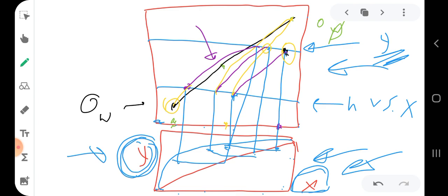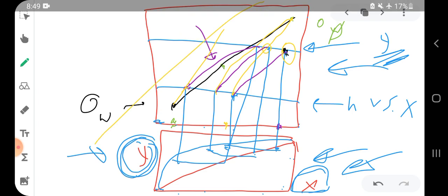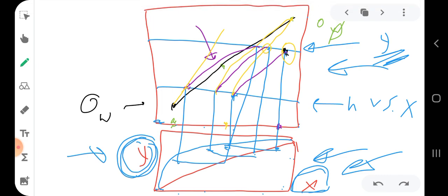Okay? And when I connect it to OW, I extend the line until I cross the vapor line. Okay, so again, I cannot connect it to OD. No, I cross the feed, so I connect it to OW and extend this line. Because I have 2 points, I can extend the line all the way for the whole graph. Okay, so the intersection here with the vapor, I do the same thing.